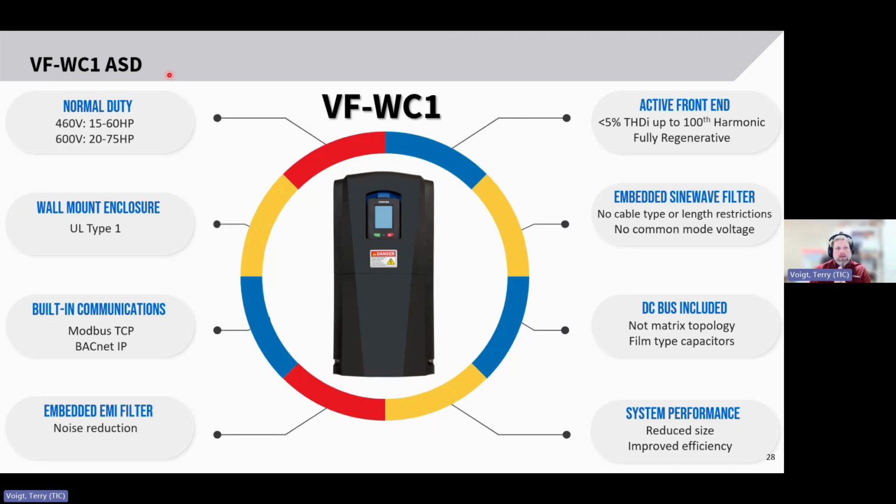And yes, Modbus TCP and BACnet IP are built in. They're included. I believe the RS-485 versions are also going to be included as well. So the Modbus RTU and also BACnet MSTP. Those will also be included with the WC1.